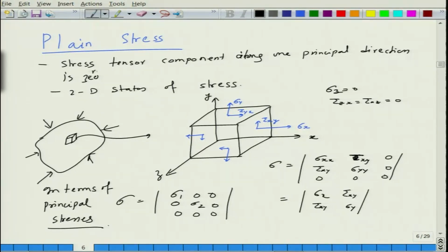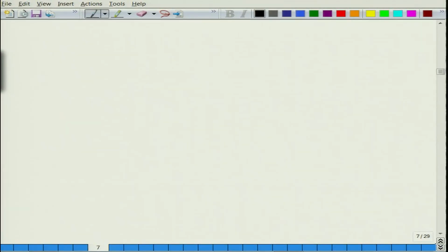So, this is the stress states. We should have ideally discussed this in case of elastic deformation, but just to introduce the states of stresses. So, this is what it is in terms of plastic deformation: you have formation of a neck at UTS, the sample undergoes non-uniform deformation, there is a cavitation at the UTS point, and those cavities, as you stretch the